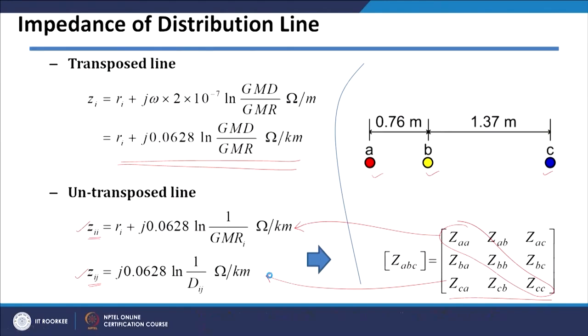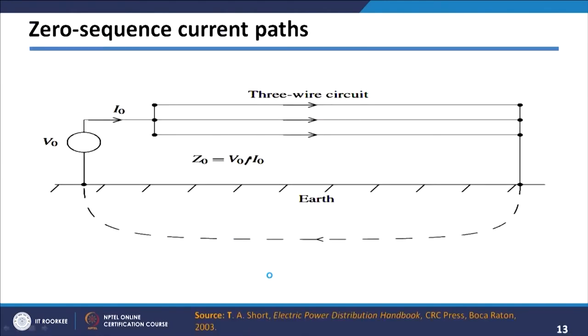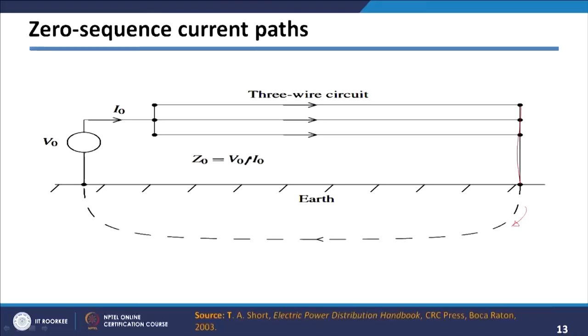Basically, if you see this particular figure here, generally what happens whenever there is unbalance in current, that unbalanced current will flow to the earth. So, if there is no neutral, there are 2-3 different conditions. In this condition we are considering a 3-phase 3-wire system where there is no return path through the neutral wire. In that case, if the grounding system is here and the substation grounding is here, your unbalanced current or zero sequence current will actually flow through the earth path and come here.